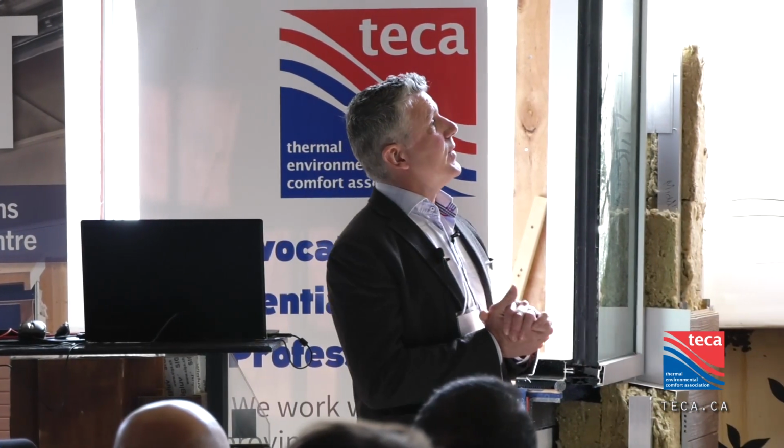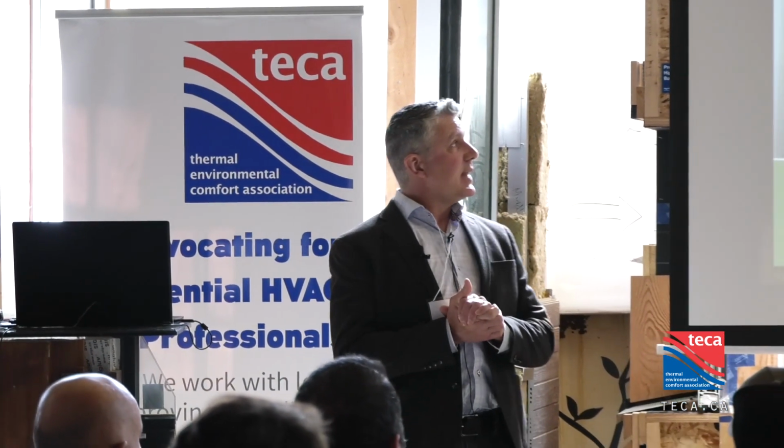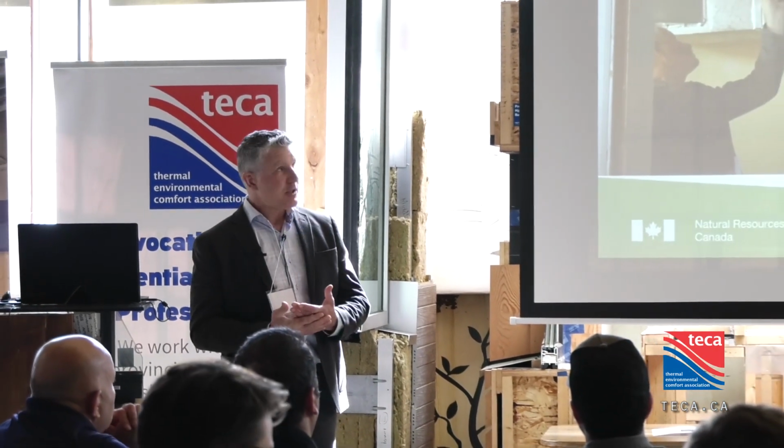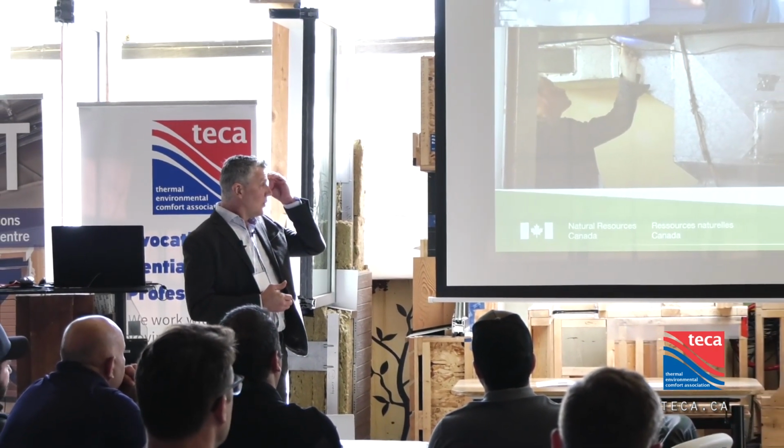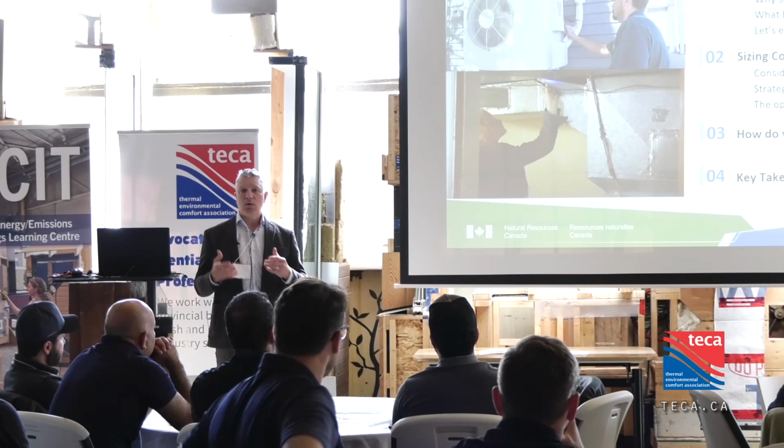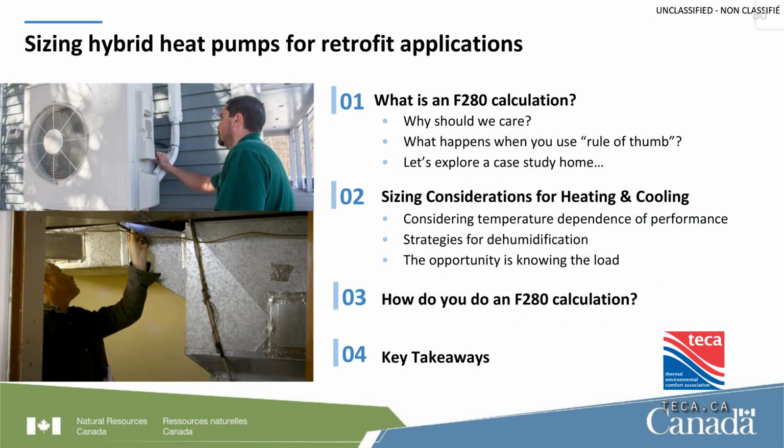Okay, so for today, what we're looking to do is we're going to look at what is an F280 calculation, why should we be using it, and what happens if we use that versus some of the older techniques as well. We'll be looking at sizing considerations for heating and cooling, and of course we're gearing all this towards heat pumps, and considering the temperature dependence of performance.